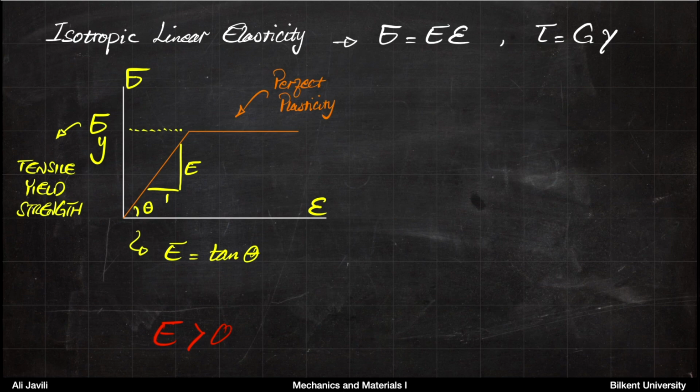Okay, so let's just finish this by now extending that linear elasticity to inelastic material behavior. And then again, we are only talking about perfect plasticity, and this is valid if we talk about ductile materials. So if your material is ductile, and if you want to think what happens if we reach the yield stress, we idealize the material behavior by this graph.